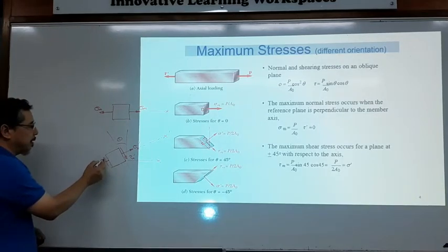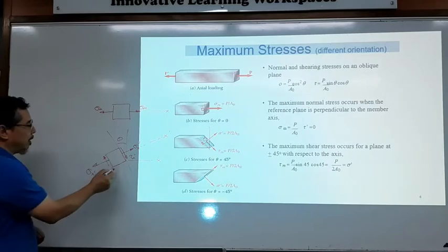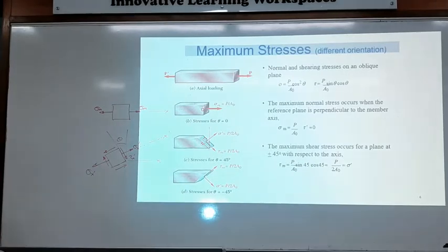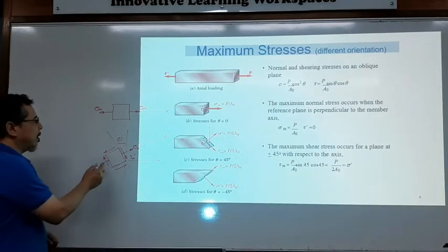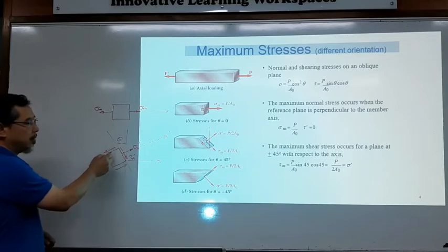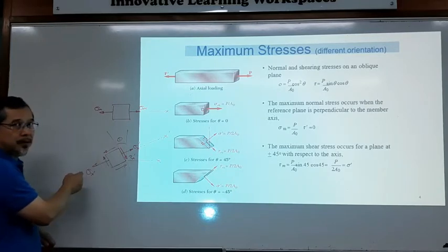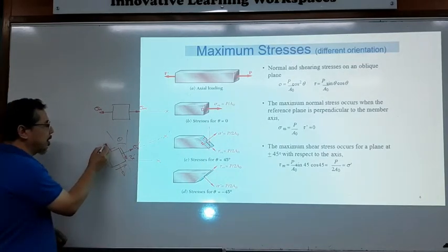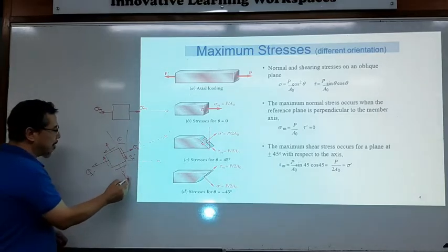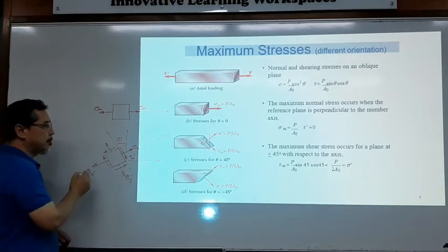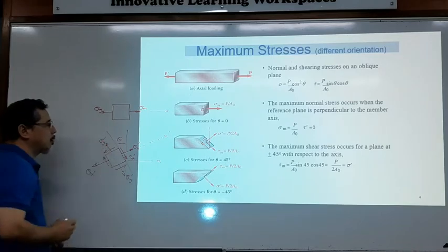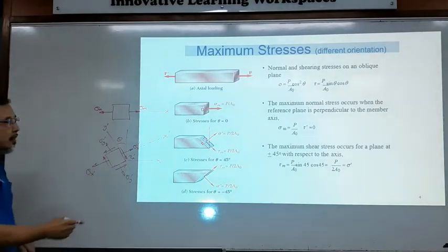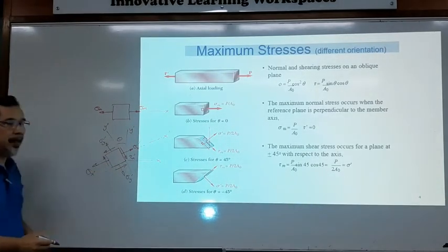So we have complementary shear stress here and also on this surface. And on top of that, because this is a slanted surface similar to this one, we will also have components of normal stresses. So we have sigma y prime, considering this is y prime direction and this is the y direction.